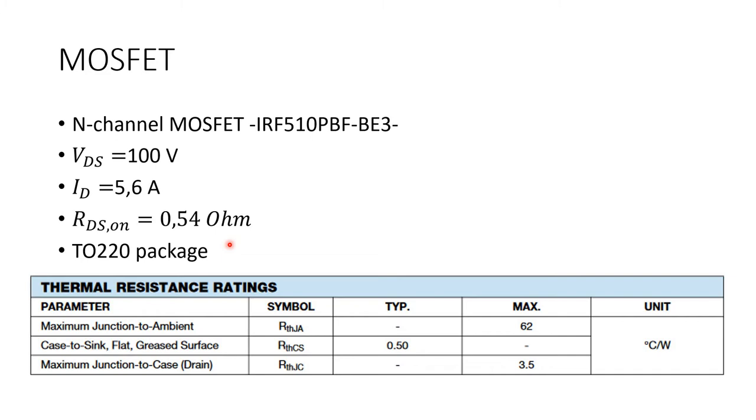I have chosen a MOSFET for this application, an N-channel MOSFET. It has a drain source voltage of 100 volts and an RDS on state resistance of 0.54 ohm. It has a TO220 package which is going to be used in following slides.